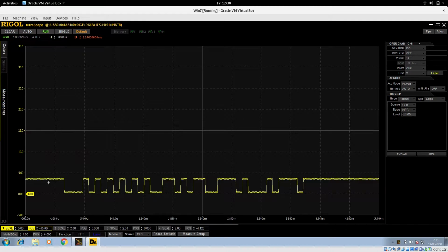It's not strictly RS232, but it's a serial RS232, like it's only 3v3. And that's our serial communications. So in the idle state, the voltage is high, that's a 0 on the line, a logical 0. And then when it drops down to 0 volts, that's a logical 1. And that dropping down is the start bit as well. So that's telling whoever's listening on the line, we've got a start bit. So that's the serial.